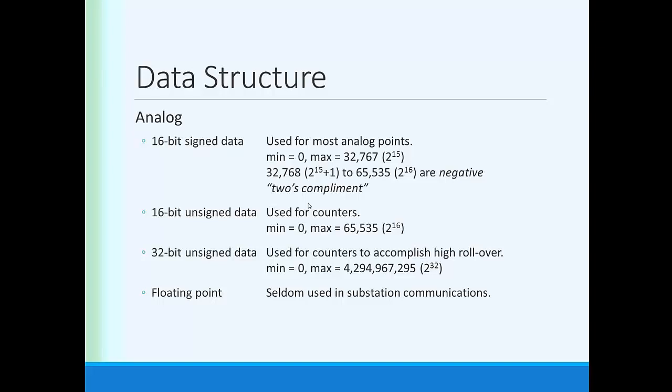And then it'll count up to almost 4,300,000,000 counts before it rolls over. So it gives you the ability to continue running that odometer in your car past 100,000 miles up until the actual life of the car, if you will. With a power plant, if you're measuring the output in megawatt hours, you might need 32-bit data to convey that information.